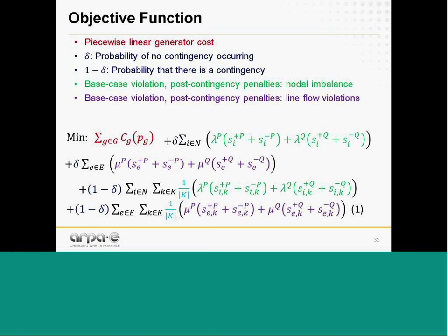There are not going to be relaxations on voltage limits, where there are going to be very precise procedures as to how we evaluate somebody with a rounding error for a voltage limit. Frankly, the best thing to do with a hard limit on the voltage for a bus is build in a very small buffer relative to your rounding, because the structure of penalty that we're going to impose for infeasible solutions will push your objective function up dramatically, as opposed to the fact that if you're at 1.099999, the impact on your cost for that solution is very minuscule relative to being tight at 1.1, okay? So that's some suggestions, all right?